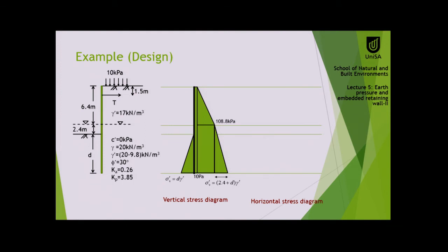Okay, before going on, if you check, first we identify that it is anchored to the retaining wall. Then what are the changing points on the left hand side? The changing point is the starting point, that is, start with 10. Then we might have a changing point for T, but it's not in the soil, so we ignore that. We come up to the water level, that is the changing point. Then on the left side there is nothing changed, so it goes directly to the bottom.